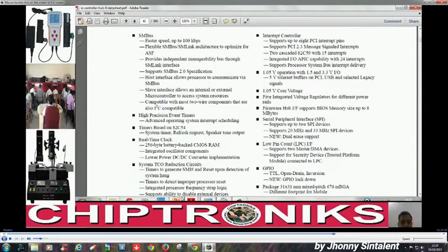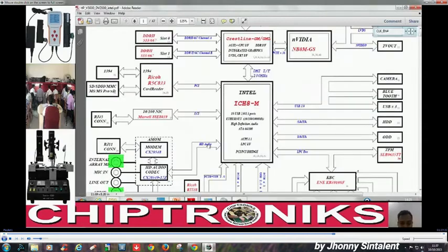Do not get confused. You see over here, this Intel ICH chipset has a lot of transistors, MOSFETs inside it. So 1.05 volt is the core supply of this chipset. Any chipset will have core and I/O, core and input output. There is a separate voltage for the core section, and a separate voltage for the input output section.